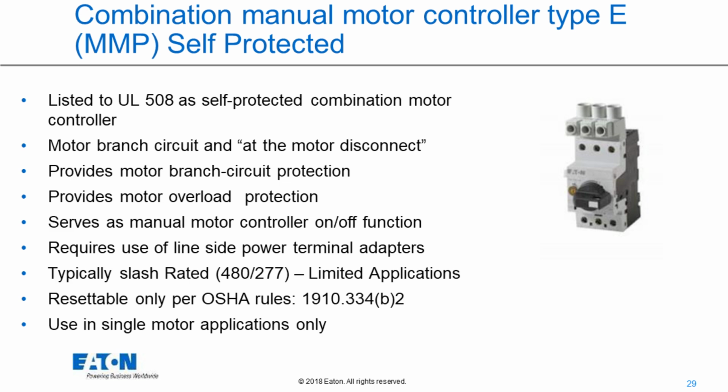It's typically a slash-rated device, 480/277, limited applications to solidly grounded Y systems only, resettable per the OSHA rules, 1910, use in single motor applications only.